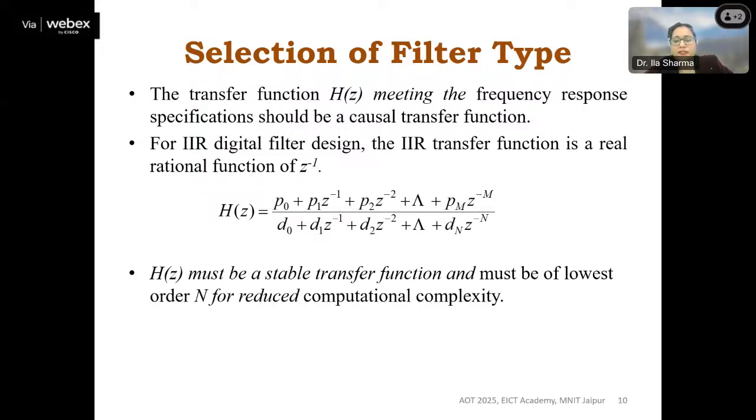You know all-pass filter, so that in combination with IIR filter is being used as a phase nullifier, and then it can act as a stable and linear IIR filter. So again, this is the choice of the engineer, what he chooses, and there is a trade-off between them.